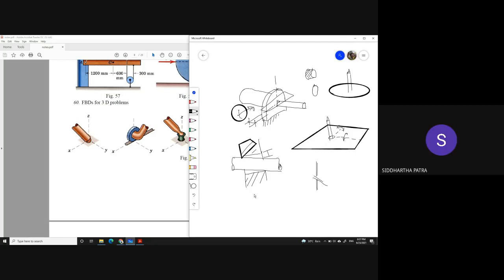Yes. Here also, let's say if it is a very small clearance, there is a clearance but very small. Now think in this way: if it is a quite wide support, practically you would not be seeing any amount of rotation. But if it is a really thin support, possibly it doesn't restrict rotation as much as it would have had it been much wider. That's the idea.